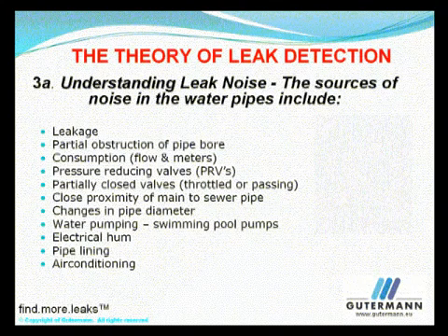When power transformers and high voltage lines are close to a pipeline, a low-frequency humming sound can be heard on the pipe. The ability to recognize these sounds enables a good operator to understand the readings generated by the Aquascope and develop strategies to overcome problems like using filters, closing valves, or returning during low flow periods.